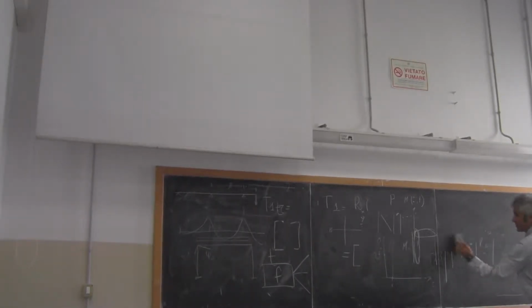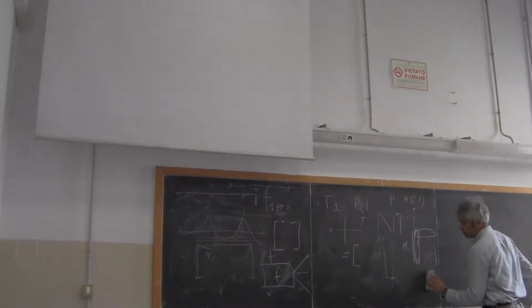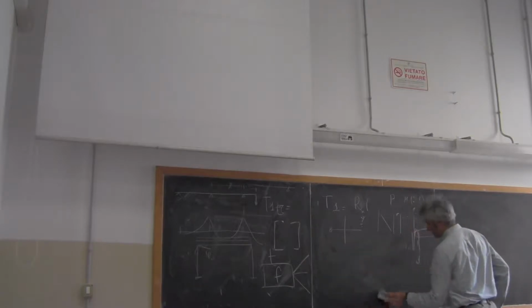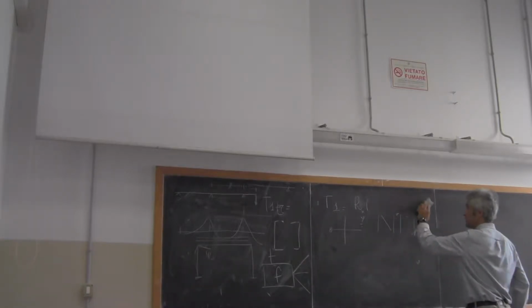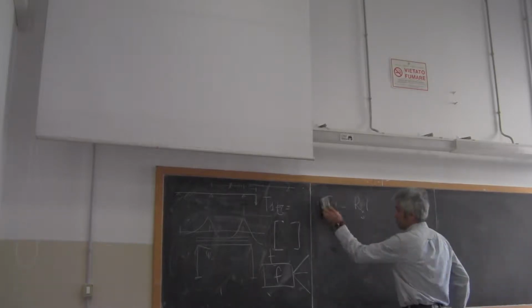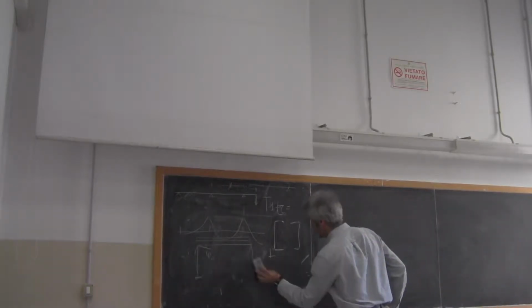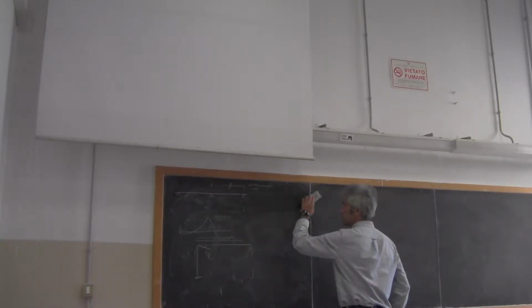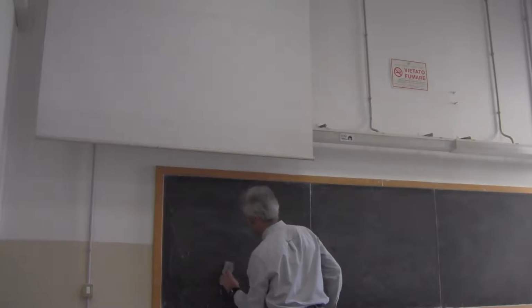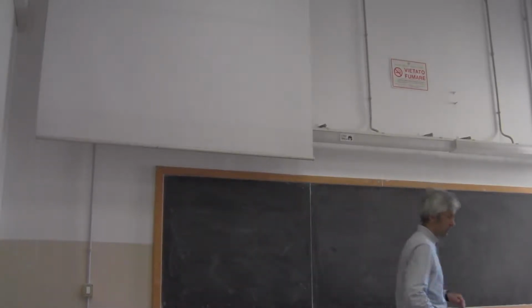As I said, we are almost done, but still I would like to go back to saltwater intrusion because I was not fully happy with the lecture that I gave on Tuesday, and in particular I was not fully happy with the fact that I used different symbols with respect to what is reported in the web pages. So if you don't mind, I would like to go back to the proof that I proposed to you in order to locate the position of the saltwater wedge.